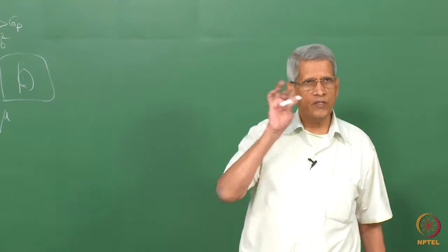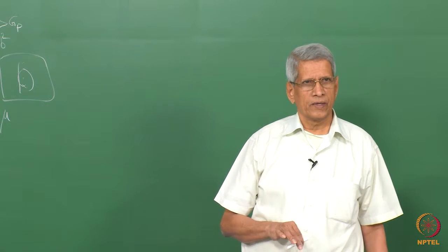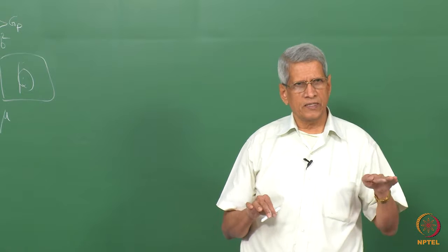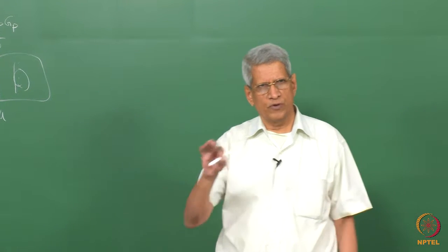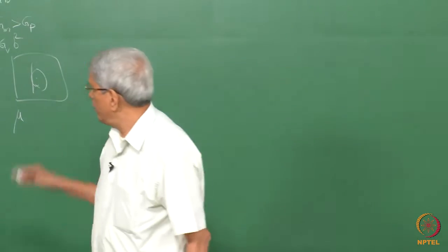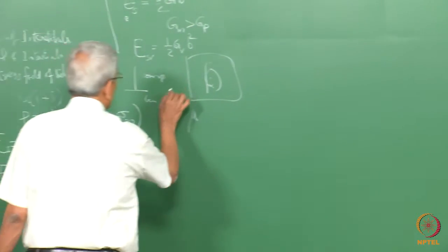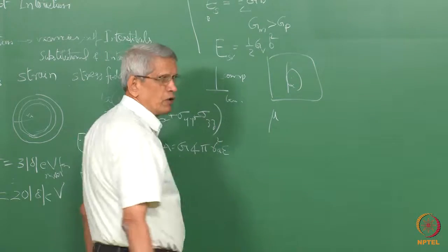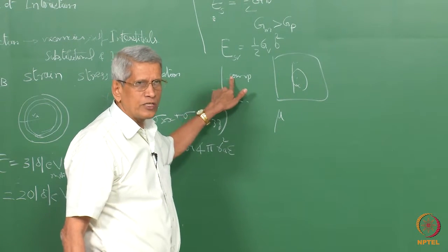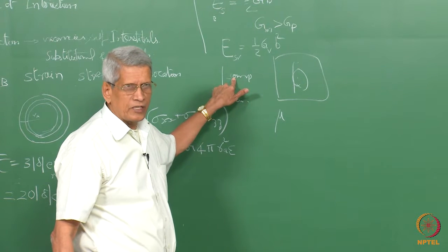But if the defect is able to migrate, that is, the temperature is such that these defects are able to diffuse, then as they go along, when they come very close to a dislocation, they will get attached to this region because the interaction energy becomes negative.